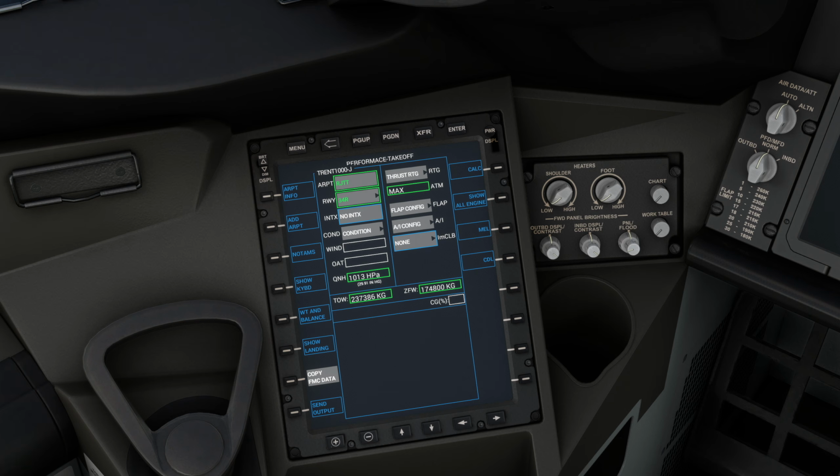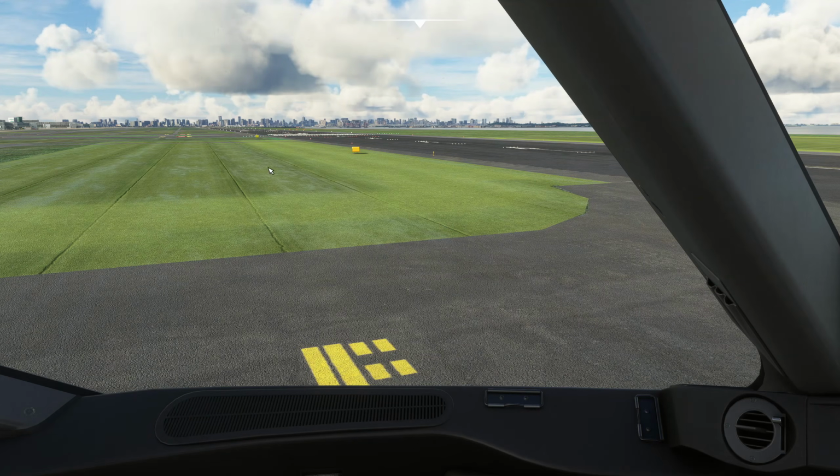We do this to save fuel, it saves noise, it saves emissions, and it actually saves engine wear, so they're more reliable in the air, which is exactly what we want. So in an Airbus, you can only depower the engines on takeoff to a certain point. So if you're on a full massive runway like this and you've got that low power setting, it still takes off very well and it has plenty of margin.